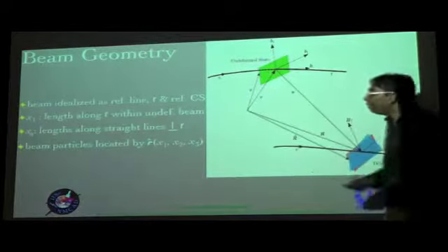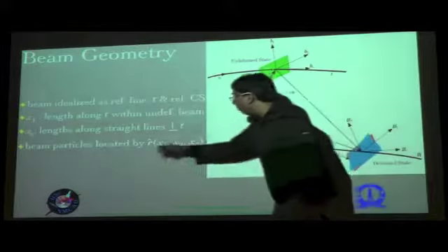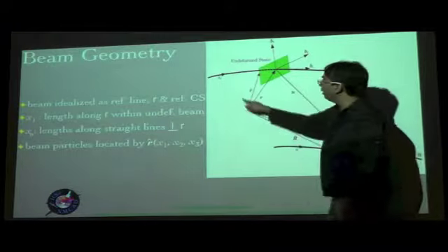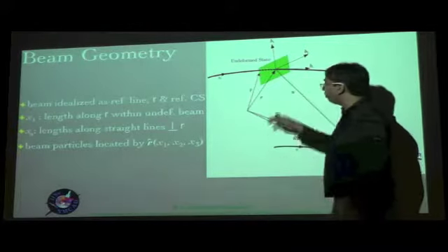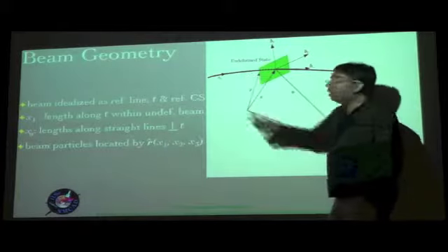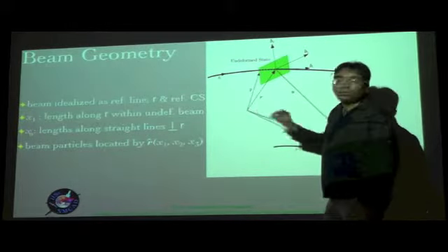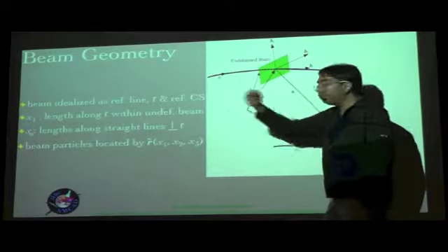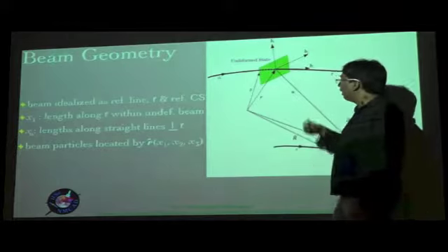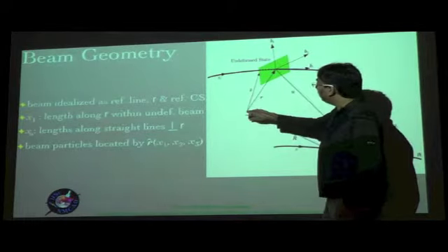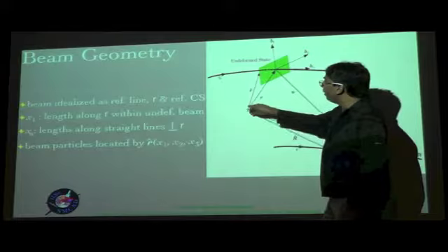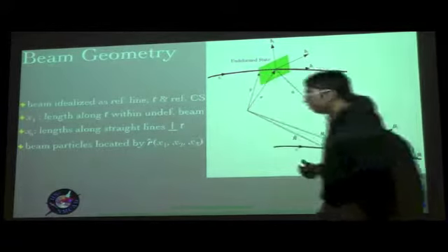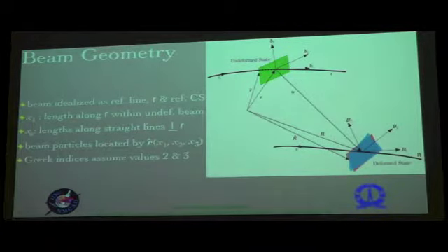It's not necessary. The beam particles are located by R hat, from some point in another reference frame A, which could be the aircraft-fixed frame or helicopter-fixed frame, whose motion in an inertial reference frame is already known, because we know the flight dynamics of a flying vehicle. So from that point fixed in the reference frame A, we have this arbitrary material point located by R hat as a function of all three spatial coordinates apart from time.